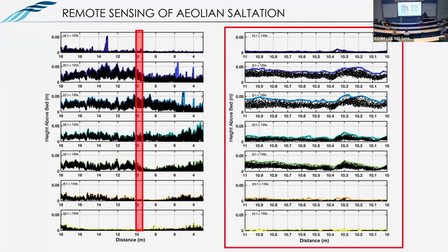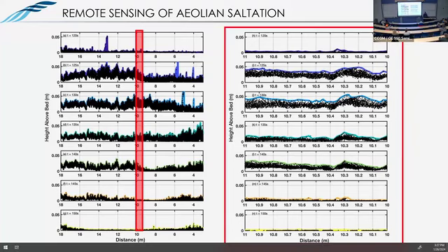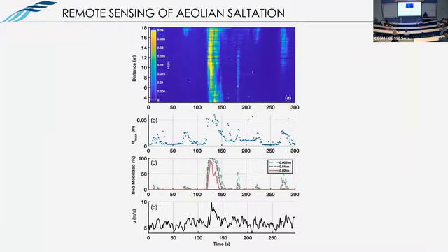But I just wanted to show an example of something that was zoomed in pretty considerably. Here we're just looking across a meter of beach. All of these points are individual returns. And notably, if you have a high resolution sensor aggregated over 1 second, we're getting a lot of point returns. And so we see a lot of structure across the beach in terms of variability and how high off the bed individual particles are getting. We've been asking downstream questions about how the bed controls local ripples, changes in grain size characteristics and moisture, and how these affect the height of the bed. So asking some pretty detailed process-oriented questions that relate to sediment mobilization that we can implement in our models.